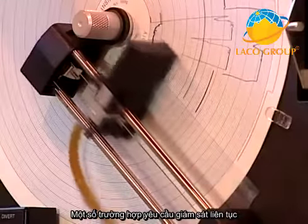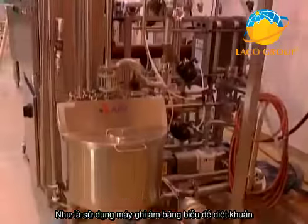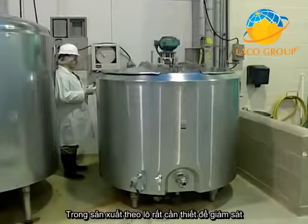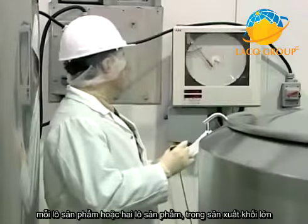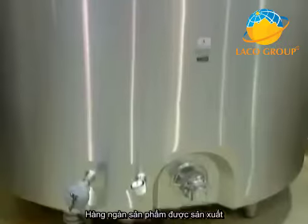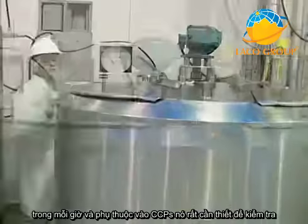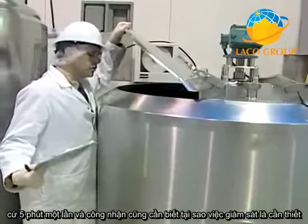Also, in some cases, regulations require continuous monitoring, such as using a chart recorder when pasteurizing milk. For batch processes, it may be necessary to monitor every batch of product, or every second batch in large volume production, where thousands of kilograms of products are produced in an hour, and depending on the CCP, it may be necessary to monitor every 5 minutes.